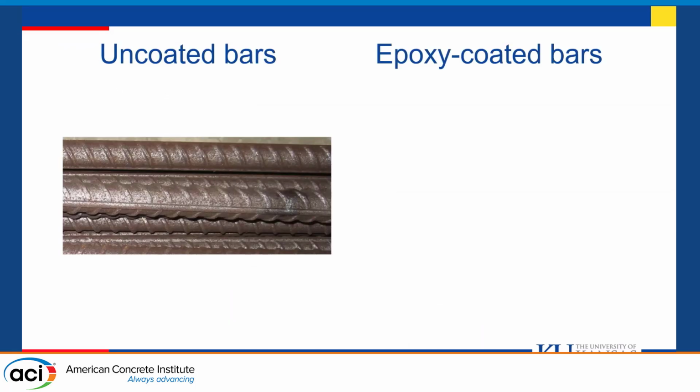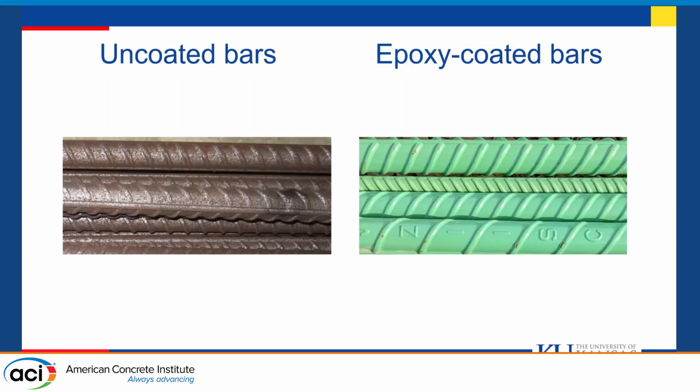Uncoated bars. As we all know, uncoated bars are most commonly used in reinforced concrete, but they are more likely to corrode. So there come epoxy-coated bars, which have a protective coating and prevent the corrosion. However, it reduces the bond strength between the concrete and bars.